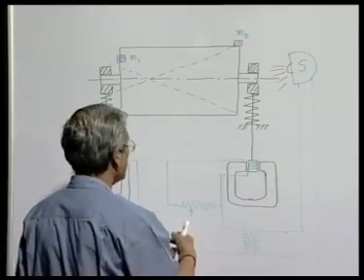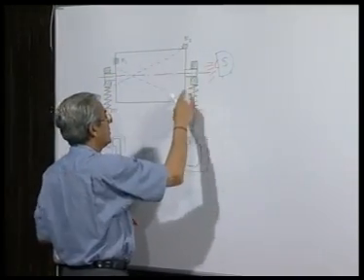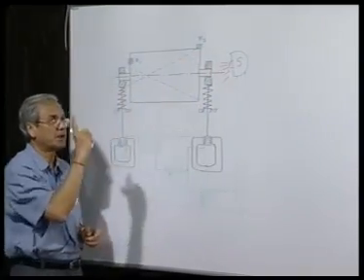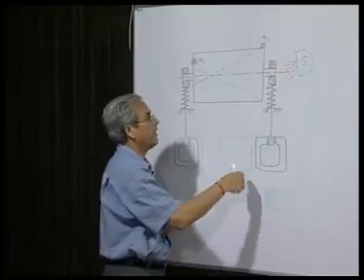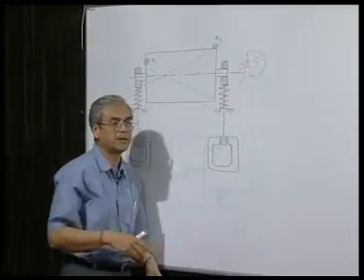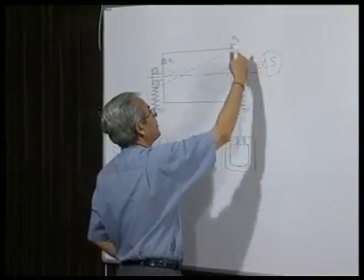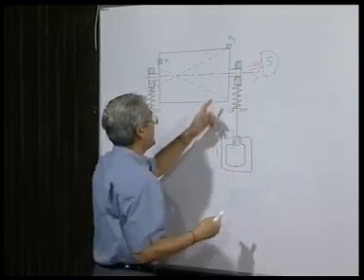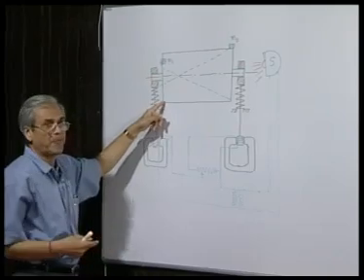It is arranged in such a way that when this is at the top position in its vibration, it flashes. So, you can see the angular position. If it rotates at reasonably high speed, the flashing will also be at reasonably high speed, and you can see the marking, generally a protractor kind of arrangement, which will show you the angular position when this is at the highest, or where M1 is the lowest.